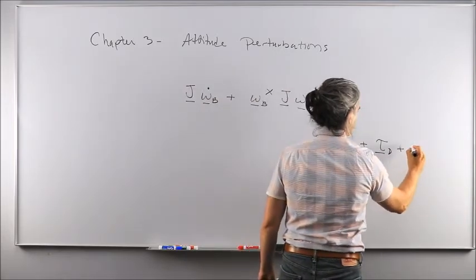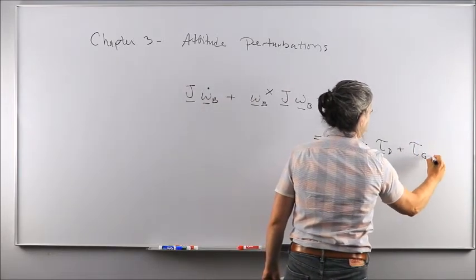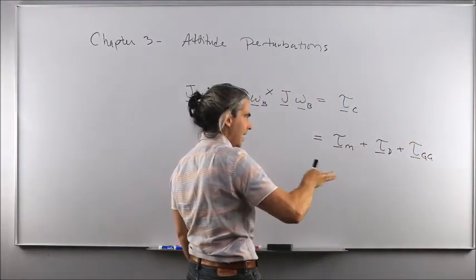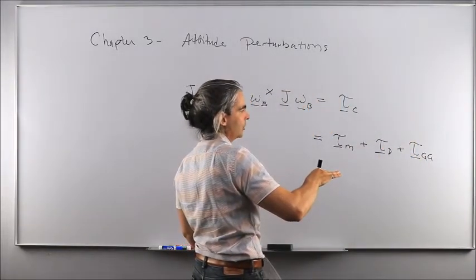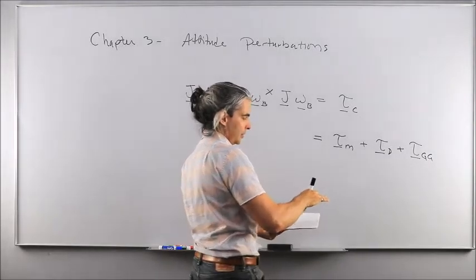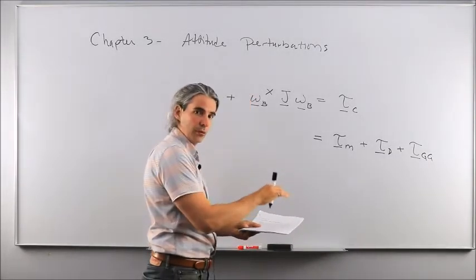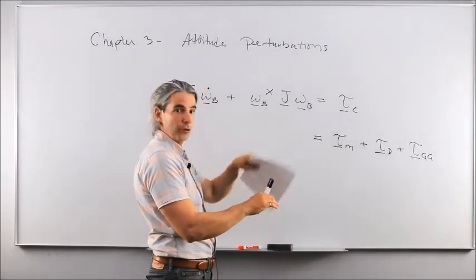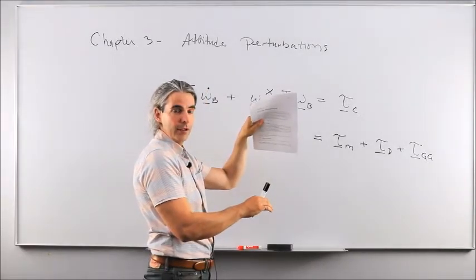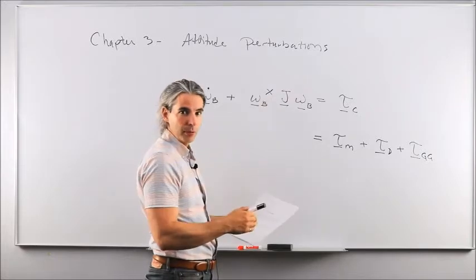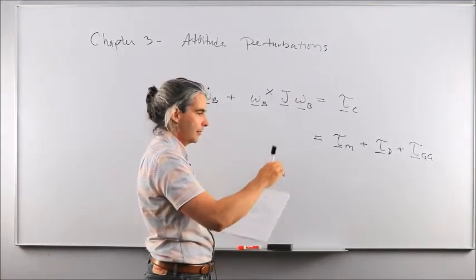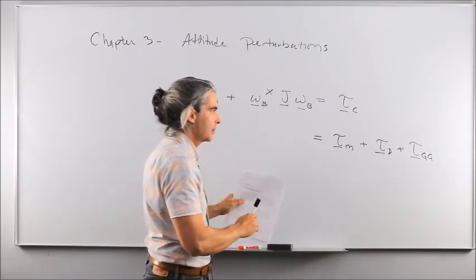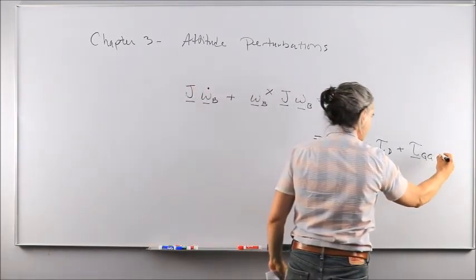We're going to look at gravity gradient torque, which will always align the spacecraft along the specific axis due to the fact that the bottom part of the spacecraft will be more attracted towards the ground or towards the Earth as the upper part, because the further you get from M1, the less the gravitational pull will be. So that difference in gravitational forces at both tips of the spacecraft will tend to torque the spacecraft, okay?